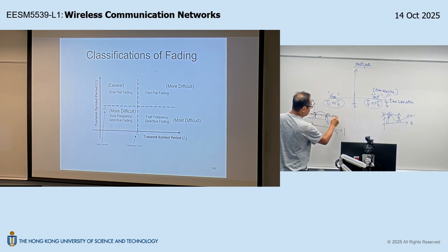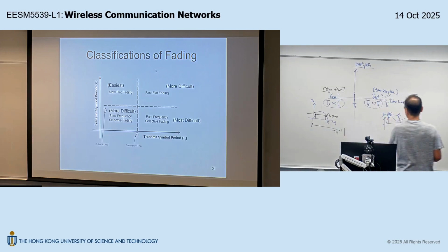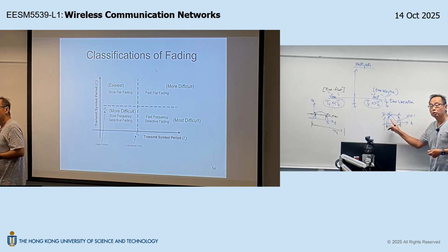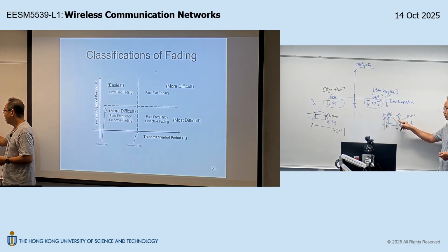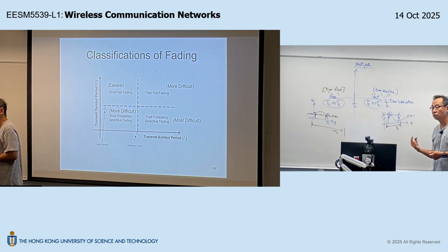So this is alpha t. That's why this is called slow fading, or another adjective for this is called time flat fading. Time flat means that the fading response is almost quasi-static within a modulation symbol. That means when you transmit a symbol, the entire symbol will experience only one alpha, only one response. This is in contrast with this, right? In here, when you transmit a modulation symbol with duration Ts, within a modulation symbol, the symbol is going to experience different fading. Okay? So you will have a different distortion associated with these two effects.